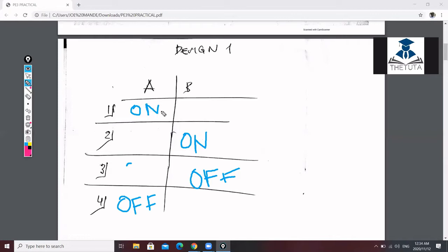Cylinder A was on, then cylinder B went on, cylinder B went off, then cylinder A went off. So you can see that there is a link between the two. They are depending on each other. Automatically we don't need a storage because they're depending on each other. We don't need to put the storage between the two. That's the first reason. So let's go back to the case where we have to put the storage and see what happens there.